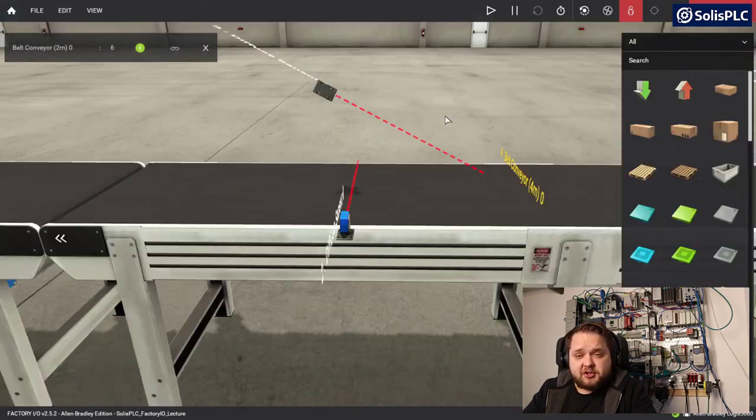Before I can write the logic for this application, I obviously need to bring in the signals into my PLC, and so we need to read both sensors. We also need to actuate the conveyors. This is something I've already enabled in the logic, but we do need to make that happen. Remember, when I start and I stop on the control panel.